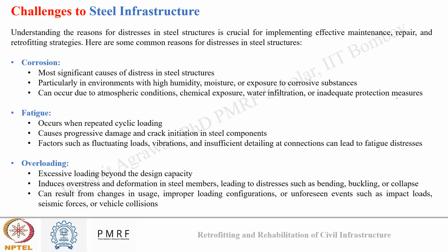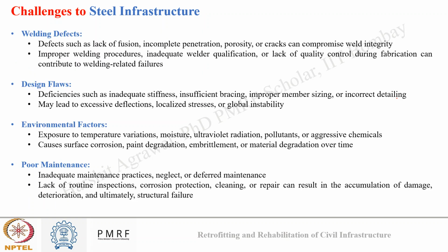This can result from change in usage, improper load configuration, or unforeseen events like impact load, seismic forces, and vehicle collisions. Further, we have welding defects, which can occur due to lack of fusion, incomplete penetration, porosity, or cracks in the weld integrity, and this can result due to improper welding procedure, inadequate welder qualification, and lack of quality control